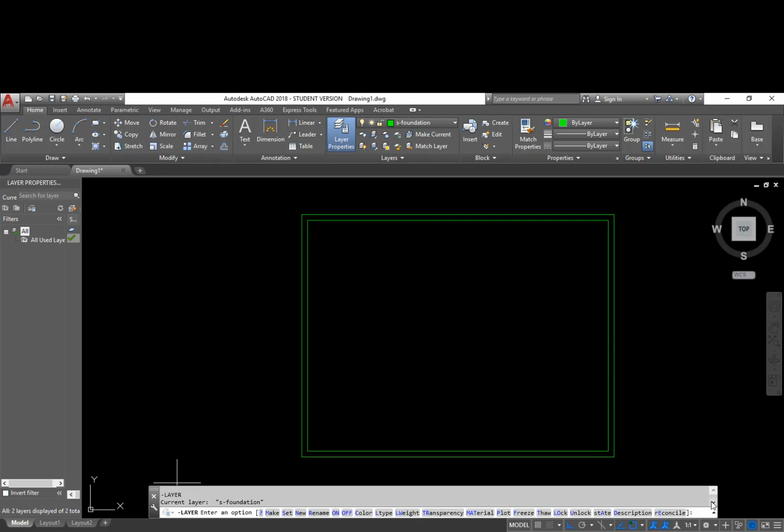The other thing I want to point out is whenever you look at these on the screen, you notice that this is a capital M, A, K, E with a blue capital M at the beginning. What that really means is it's showing you what you have to type in right now for one of those choices. So right now, capital ON and capital OFF are what you have to type in to turn a layer on or off. The reason being, if I just typed in capital O, it doesn't know if you're talking about on or off.